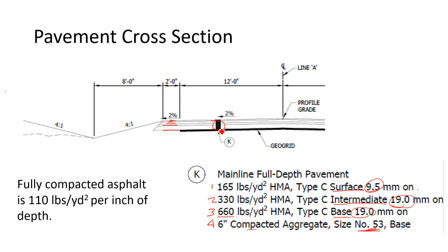And even though technically the sand may have really good bearing properties and a good modulus for bearing, they can handle a high PSI, the constructability may be really bad. We've had that problem before. Or if you've got a clean number 8 stone or something, all single sized basically, or very close to it, those act kind of like marbles, and it's really hard to drive on, and you're going to put ruts into it. And then every third or so dump truck that goes through, you have to come back through and try to smooth that out and roll it again, which is a mess.